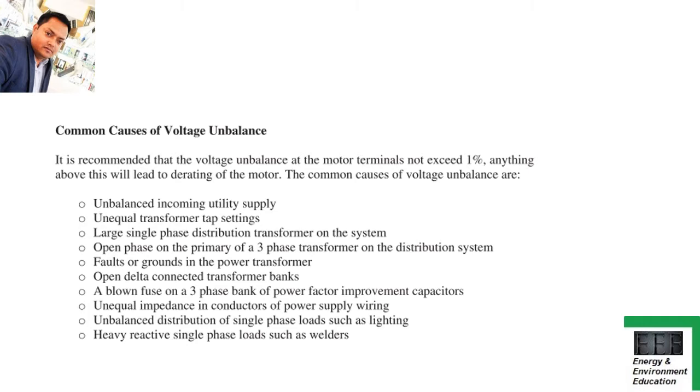Open delta connected transformer banks, blown fuse on a three-phase bank of power factor improvement capacitors, unequal impedance, unbalanced distribution of single-phase loads such as lighting, heavy reactive single-phase loads such as welders. So out of these, whichever you feel comfortable to remember, which you think is easy for you to remember, only those points you will consider. You can leave some of them, but at least five of them you must remember, friends.